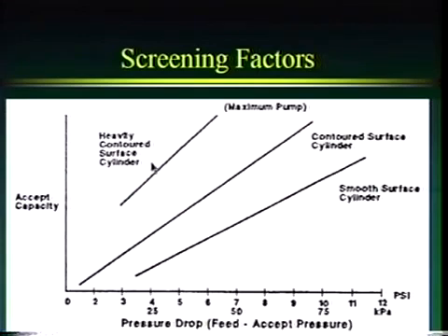But we need to realize that the contouring also realigns contaminants and allows them to pass through. So at the same slot size, contouring can decrease our cleanliness efficiency. The point there is that it makes it even more important to have smaller openings, because those smaller openings can compensate.